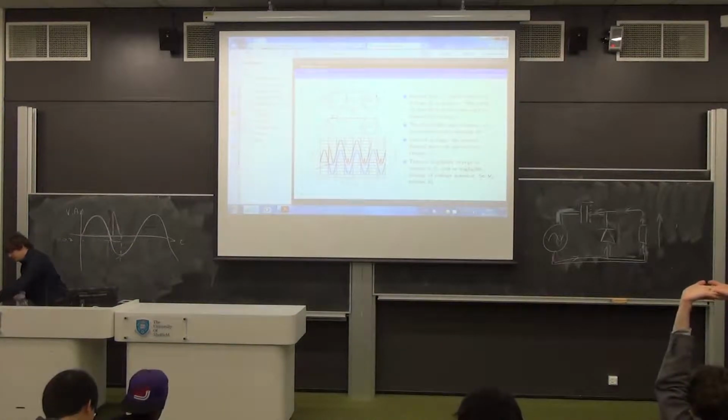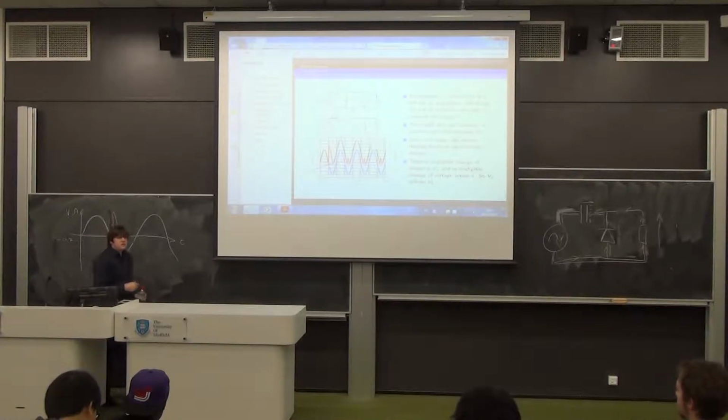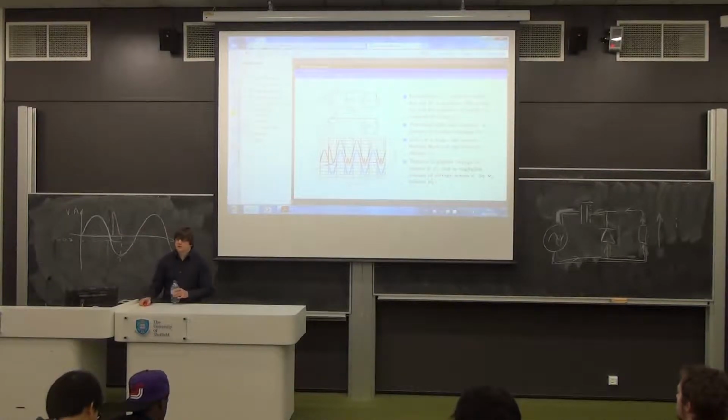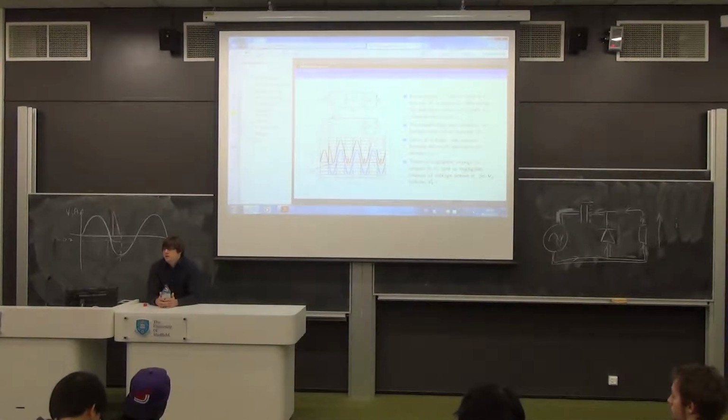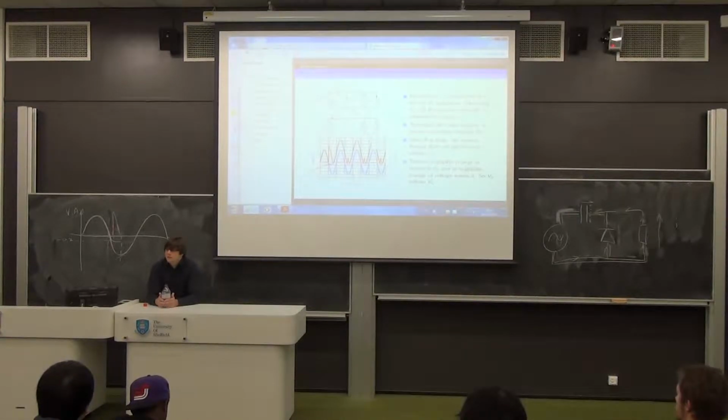The other thing to know, of course, is it's almost the same sort of thing that happens in the peak detector, in the sense that you've got a period in time where a waveform exists that causes the diode to be switched on, and that causes the capacitor to charge up, and then later the diode switches off and the resistor discharges the capacitor. It's the same set of events, actually in more or less the same order. The only thing that's changed is the arrangement of diode and capacitor mean that the waveforms look different. It's not conceptually any more troubling, although it usually does produce a lot of difficulty.